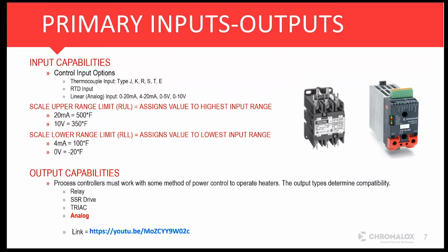And that would be maybe along the lines of an analog signal. It's very, very important in all of these controllers to scale them and how to scale them. And what I mean by scaling is there's a correlation of one, the scaling, like to what decimal point, to how granular you want your control. But there's also the side of the scaling that allows you to limit operator control.